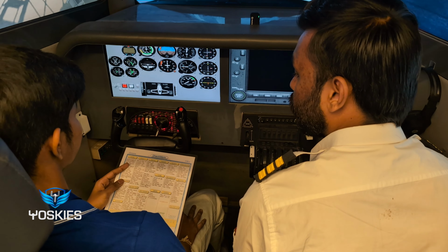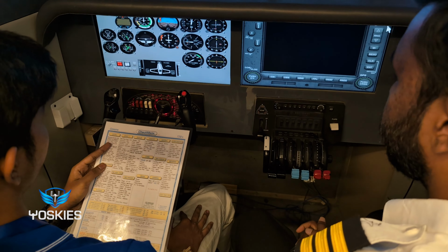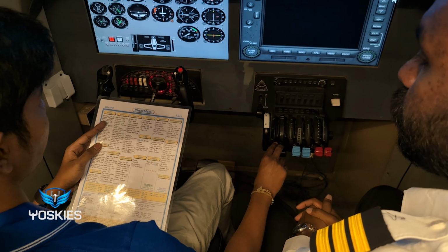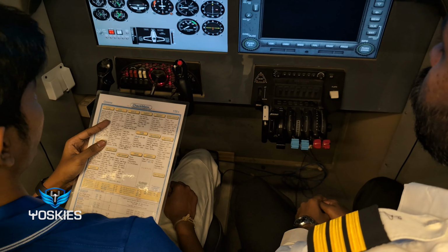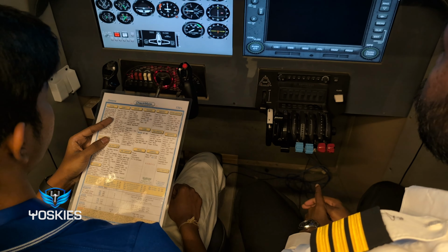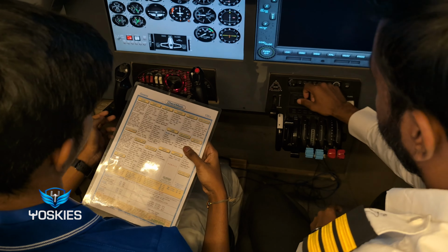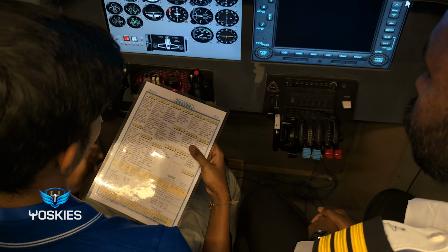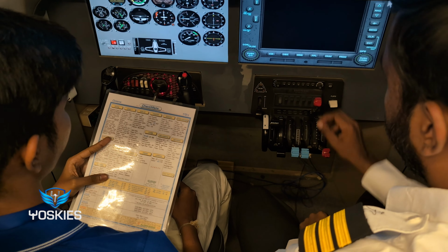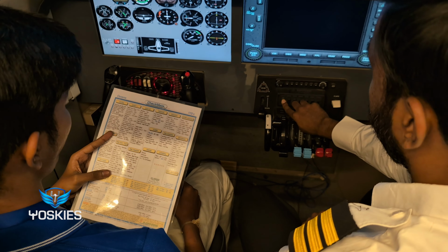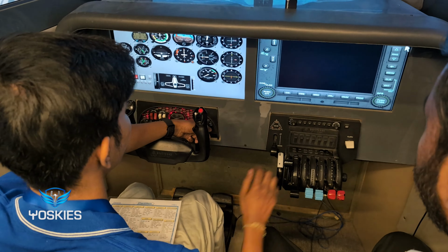Now we'll demonstrate the usage of the checklist and startup. Startup checklist: seat, belts and harnesses, check. Avionics off, check. Autopilot off, check. Throttle to 1/4, mixture full rich. Brakes, props clear, right is clear, left is clear, battery on, auxiliary fuel pump on, beacon lights on, mixture 3 to 5, 1, 2, 3, 4, 5, mixture fully, auxiliary fuel pump off, magnetos, left is clear, right is clear, props clear.